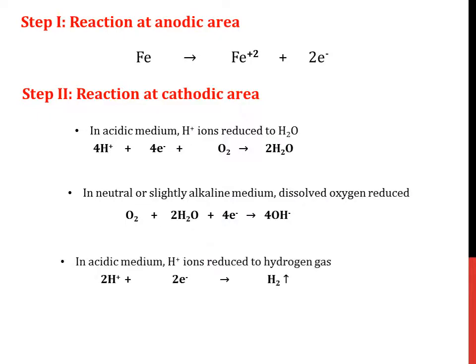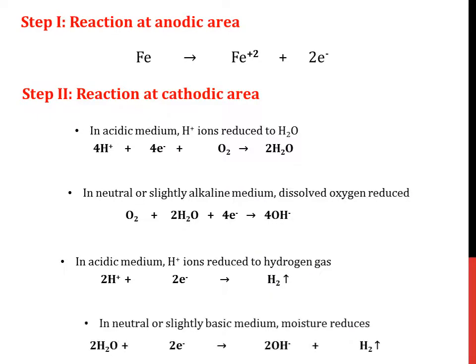In the absence of oxygen under acidic media, H plus ions reduce to hydrogen gas, and under neutral or basic condition, moisture reduces to hydroxyl ion and hydrogen gas. So if you observe the various reactions here, in the absence of oxygen, mainly it involves the evolution of hydrogen gas, and in the presence of oxygen, it involves the absorption of oxygen.